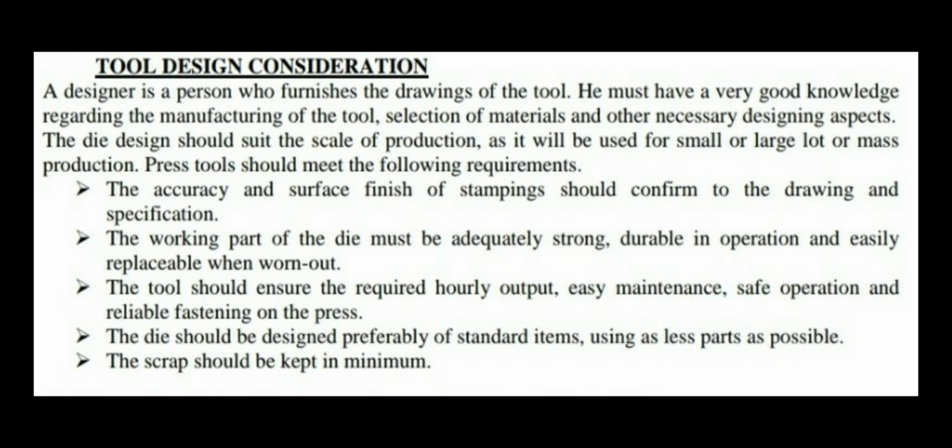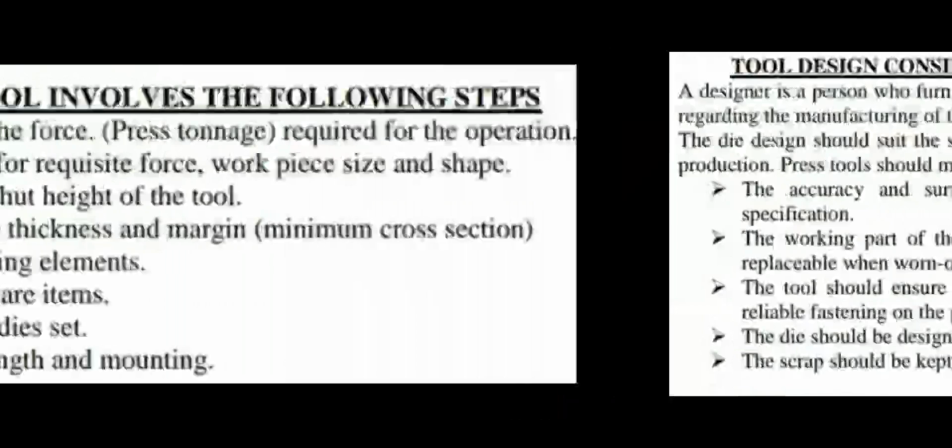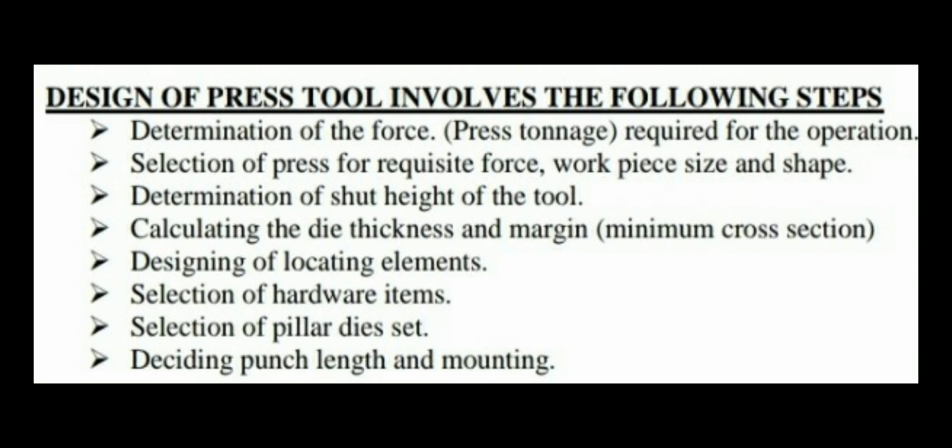The die should be designed preferably of standard items, using as few parts as possible. The scrap should be kept minimum. So these are some tool considerations. We must consider all these requirements before going for any press tool or press operations. Then the design of a press tool involves some steps.